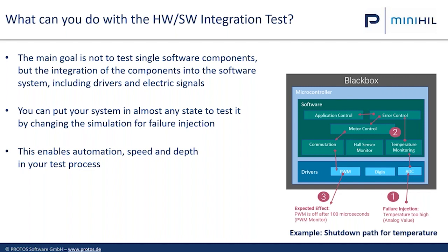That's the requirement here. And the other requirement is whether I get the right CAN error message, because, for example, if the pump or this lubrication system is attached to a crane, or to a windmill or something like that, to a wind generator, that's safety critical. So you need to know, you need this error message to react correctly. So that's what you can do as an example with such a black box test system here.